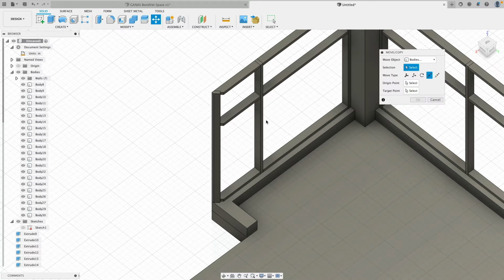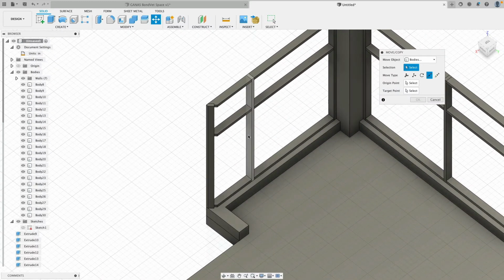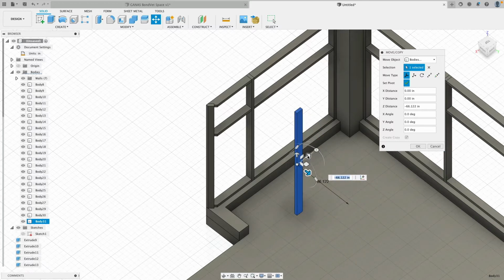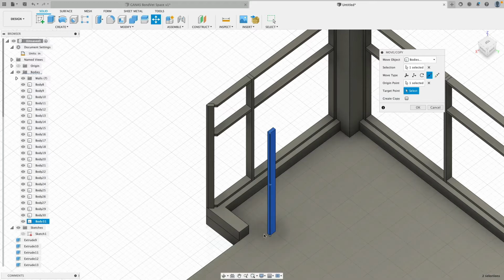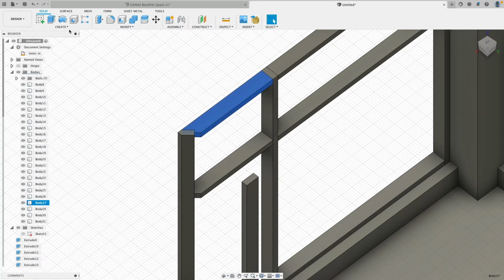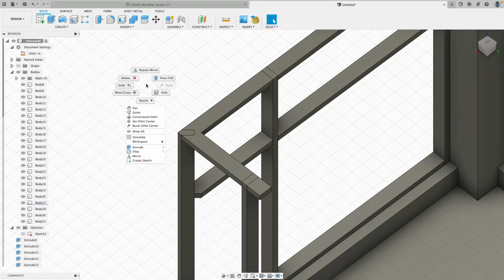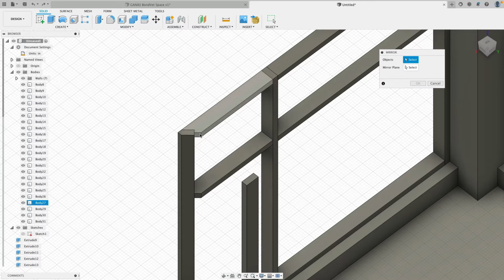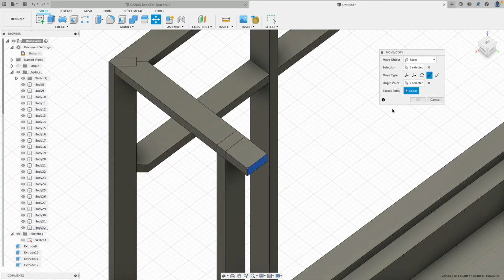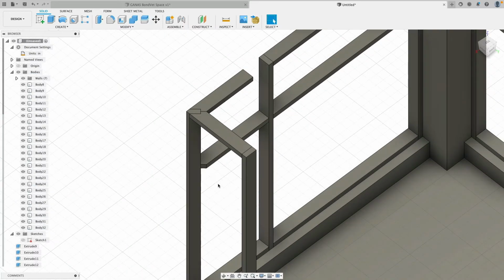It's also pretty simple. First, I will actually select this object here. No, I can select, I will make a copy. This one, move this one out. Okay, there we are. And then I go move from this corner to this corner. There. Beautiful. This one here. So this body I would like to mirror along this face. There. Oh, but not join. Undo. Right click, repeat. There as a new body. Okay, thank you. And then, as you can see, this sticks over, so we can easily simply move this face back to there. Very good.